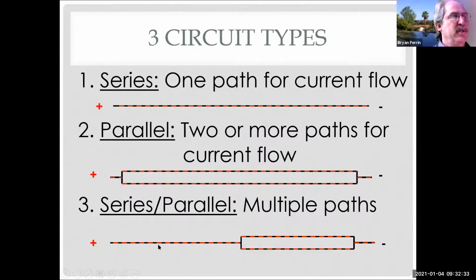So here in my series parallel, it's only a series parallel if I have a load in the series part of the circuit. And we only have a couple of circuits on the car like that. One of which would be the dash lights on your dash, where it has a resistor to dim or brighten the dash lights. And then it has what? All the bulbs. So each bulb is its own parallel circuit. And then you have a resistor that controls the current flow through all the bulbs. So that's one of the few examples that we have on a car of a series parallel circuit. They're very rare. That's also why there's much less homework on series parallel.